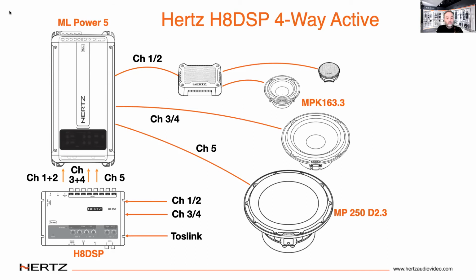If we take the door woofer off the passive crossover circuit and power it directly with its own amplifier channels, we get more power to the door woofer. We don't get any side effects from the big parts from the passive crossover. And we also get direct control of the woofer level compared to the mid and tweeter speakers. This makes tuning the overall sound easier, and it lets us get more output overall. And we can manage the transition from the door woofer to the mid-range better because we have a DSP with dedicated channels and delay on each channel.